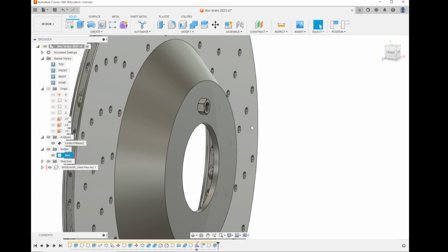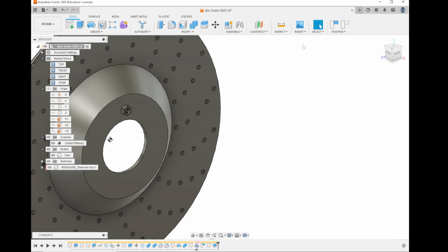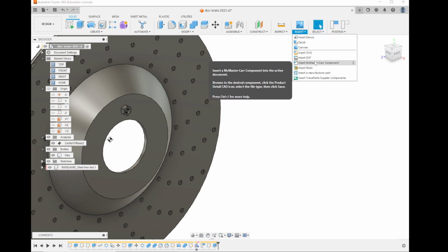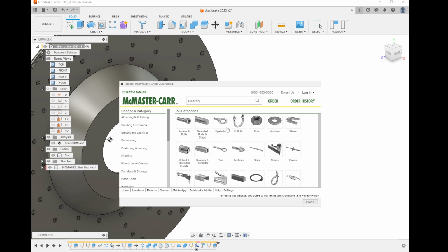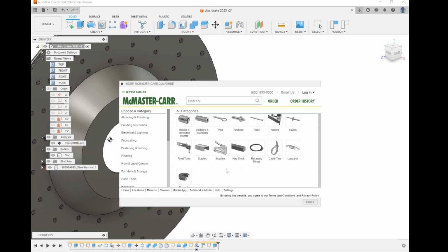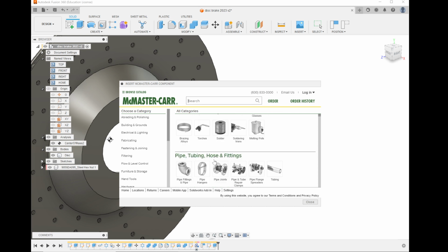Great, you got that nut there, and then you can do the same step we did before, where you do a rectangular pattern to make multiple copies of this nut. So another feature, TLDR of this, is that as you're making a component, you can insert components that already exist. You can also insert things from your other CAD designs. Where this becomes really useful is things like bearings. Oh, there are actual whole objects in here as well.